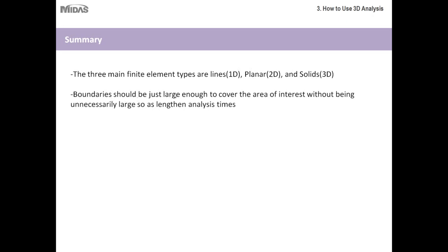Okay, then boundaries should be just large enough to cover the area of interest without being unnecessarily large so as to lengthen analysis times. Keep in mind that the larger your project model is, the longer your analysis will take. But you also want to make sure that your model is large enough to cover all of your necessary boundaries, so that all of your strains and displacements, all of your results are within the size of your project.